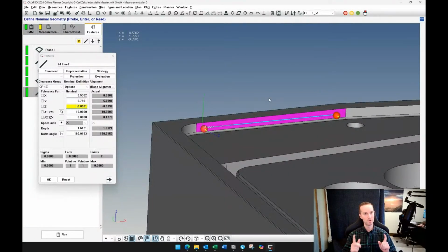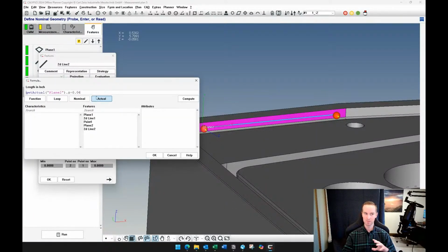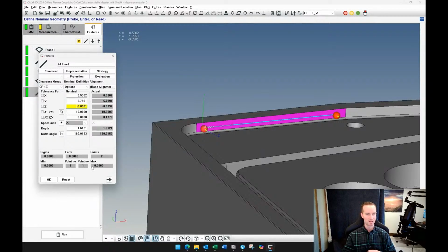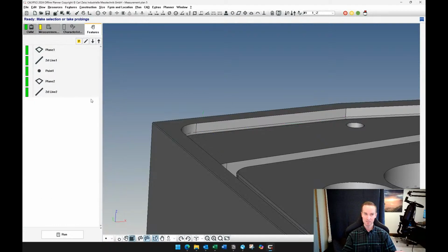There are times where the formula is not ideal. I recently did a job where we wanted to change the whole program to metric from inches or vice versa, because the machinist needed to see in inches and the drawing was in metric, things like that. The problem is with the formula here, it's not going to directly convert any of these values. So if you're running into those issues, you can just do a secondary alignment instead. It's about the same number of steps.